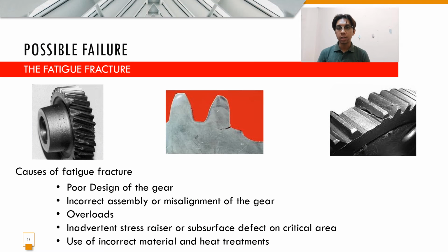The fatigue fracture. Fatigue is more commonly happening in gearing, such as tooth bending fatigue and surface contact fatigue. Several causes of fatigue failure are poor design of the gear set, incorrect assembly or misalignment of the gears, overload, improper stress riser or subsurface defect in critical areas, and the use of incorrect material and heat treatment.